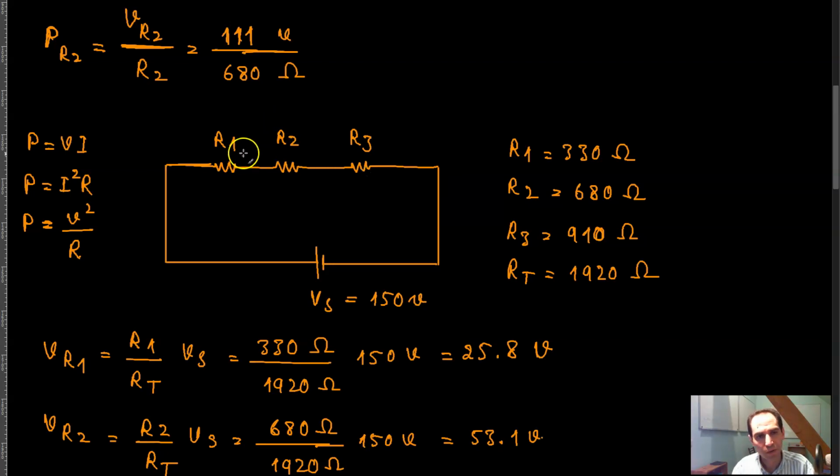Meaning that in a series circuit, the voltage drops across R1, R2, and R3, when you add them together, become the power supply voltage. And again, here, when it comes to power, the power supplied by the power supply is equal to the individual power dissipations in each of these resistors added together. That becomes the same amount, right?